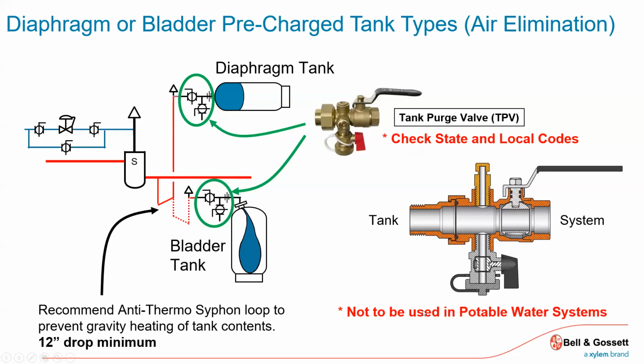Well, if that tank's connected to the live system, and someone just walks over with some type of pressure gauge and reads it, it's going to read whatever the system pressure is. You've got to isolate it. So they'll close that valve and isolate it. But then you've got to drain the pressure that's built up inside, say, that bladder. You've got to unload that so that you're truly just reading the air charge while it's disconnected from the system.